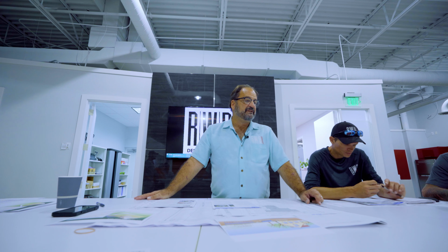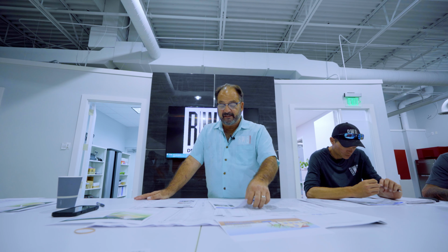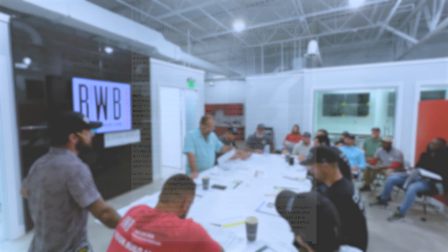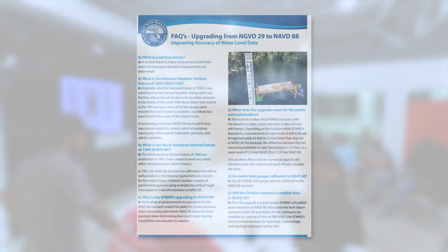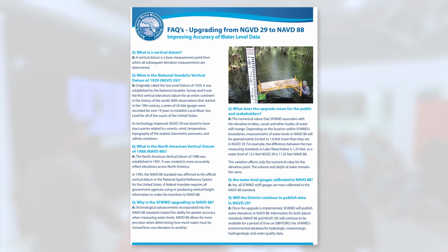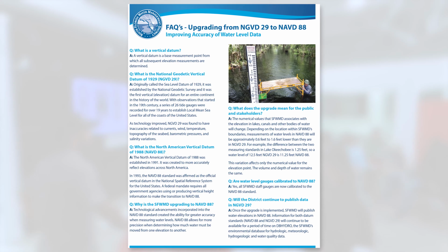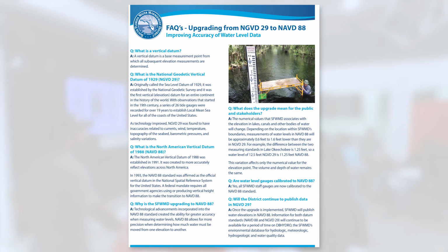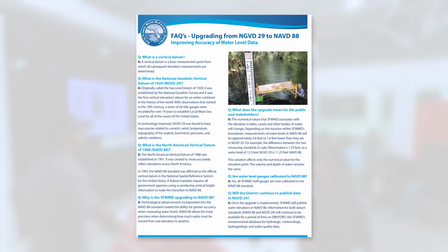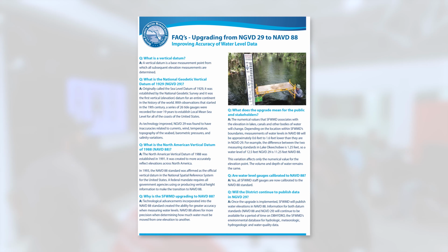It will most likely, or it should be, NAVD. This sheet will give you a better handle on exactly what we're talking about. Okay? He is going to give you a reference point. He's going to come in and give you a fixed item like a pole or concrete or something that is not going to move. And he's going to put an elevation mark on it. It doesn't have to be anything specific. It could be 20 feet, it could be 25 feet, 20, 19, it doesn't matter.